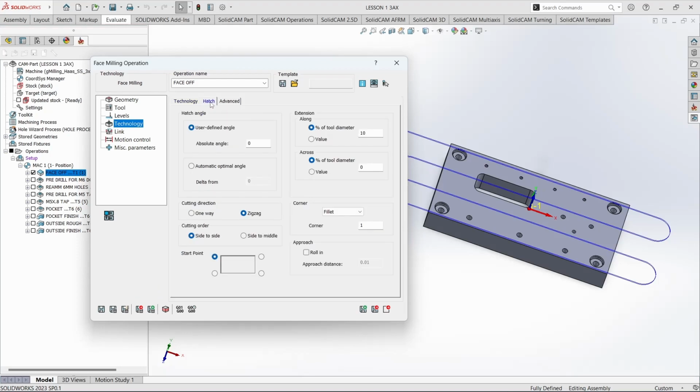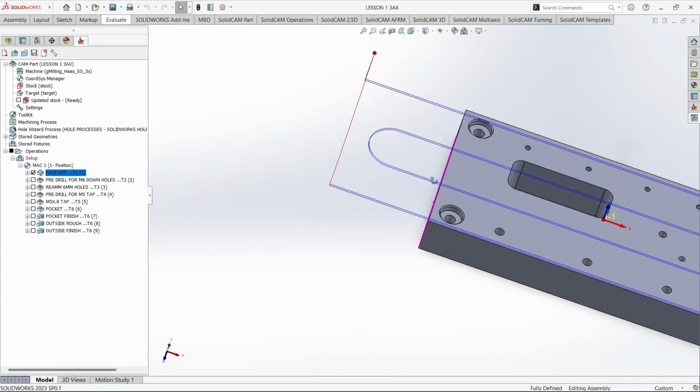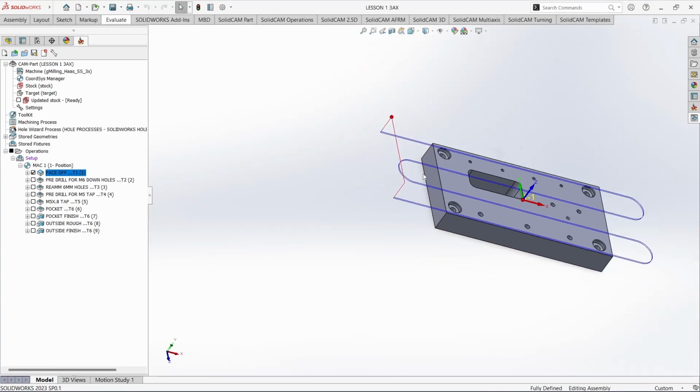Okay, okay, in here. All right, so now I realize that it's in here. So let's say if you don't have the fillet, you will see it. What I mean here, see that it is sharp, right? So if you want the tool to move smooth, you might need to put some fillet in there, whatever it is, and then you can see that the tool path is more smooth, right? So that is with the face mill.